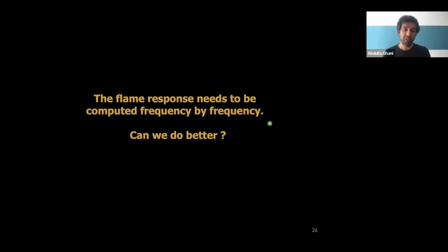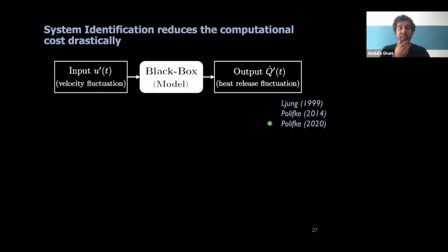So, and this is now the question that came up a few years ago. The group of Professor Polifke in Munich established this method called CFD system identification, CFD/SI in short. And what they do is they use techniques from control theory, namely system identification, where they relate input fluctuations to output fluctuations. So I will just go through that briefly, but I recommend, if you're interested in that, go to these reviews that Wolfgang Polifke has written.